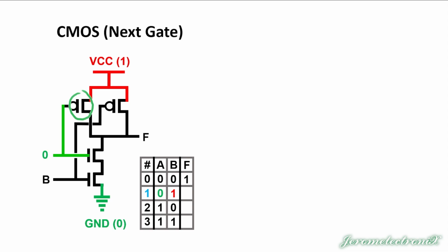Just make sure you realize that's how I am instantly able to see which one is a CMOS, which one is a PMOS, and which one is an NMOS within this greater CMOS. So a 0 in the PMOS allows flow in the PMOS and blocks the flow in the NMOS. Now the voltage can flow down toward F through that open gate, and that means we have a 1 on the output.